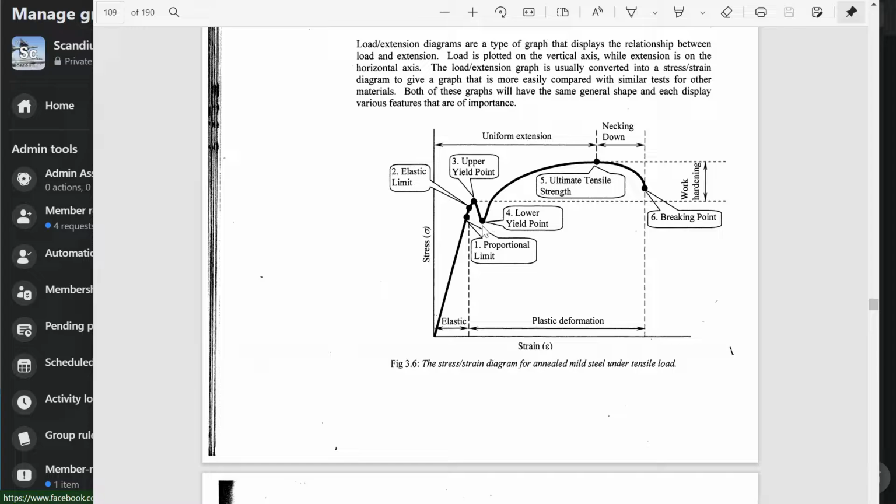The lower yield point is that there. Now those four points, I will say I was teaching for a couple of years before I really understood the difference of those things. What we typically use at uni and the practical applications in my working life is we just care about the lower yield point. That becomes our effective working stress.